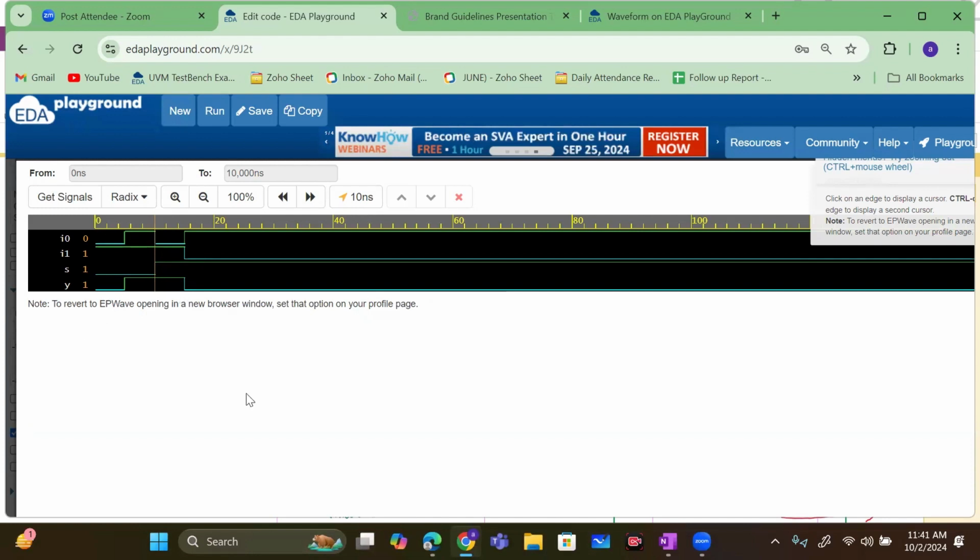So now after verification, whatever circuit we have that is verified, we can send it to the backend team. Now they will do first synthesis. They will identify whatever you use in the design that is synthesizable or not. Based upon that, they will forward it to floor planning and so on, that means the physical design team. They will just pass it out. So if any of you have any doubt in this flow, you can ask. Then I will go one step ahead.